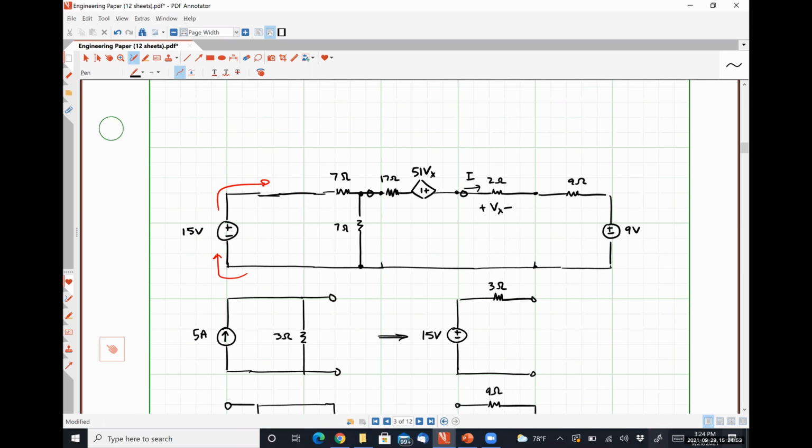So I have a practical voltage source on the left-hand side of the circuit now, right? I'm going to erase this terminal and erase this terminal. And I'm going to move this 7 ohm resistor over here so it's a little easier to see. Converting that practical voltage source places that 7 ohm resistance in parallel with that other 7 ohm resistor, allowing us to combine it.